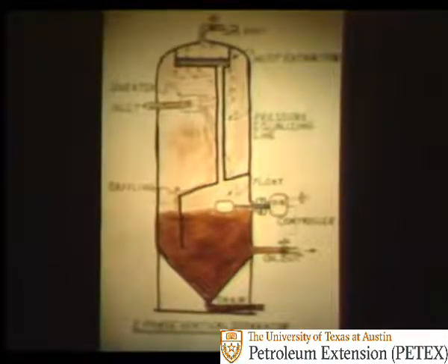The liquids fall from the middle part of the separator to the bottom. Baffling, shown in the lower portion, provides a calm area for the level control float. A pressure equalizing line from the mist extractor to the float chamber is needed to maintain maximum pressure at the liquid outlet and to drain the liquids from the mist extractor.